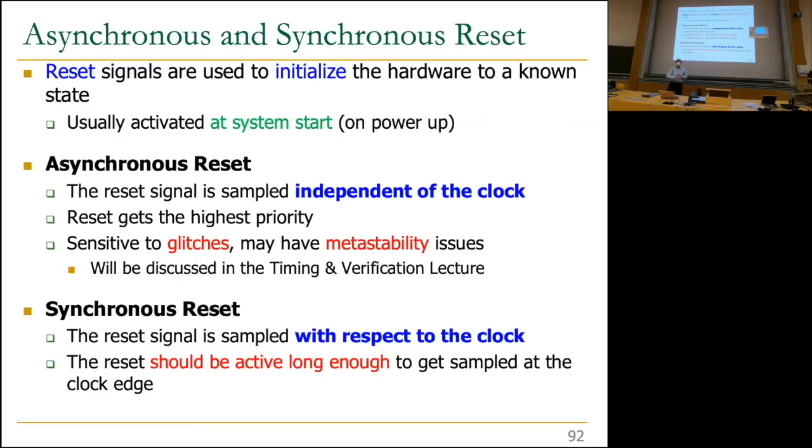When you're receiving signals from the outside, for example, the outside signals have no knowledge of the clock. So if you assume that the outside signals need to be sampled at the time the clock changes, you may be missing some of those signals. You really need to add some asynchrony to the circuit, and that's important to think about. So there's some domain that needs to transition from asynchronous to synchronous if your computer is completely synchronous.